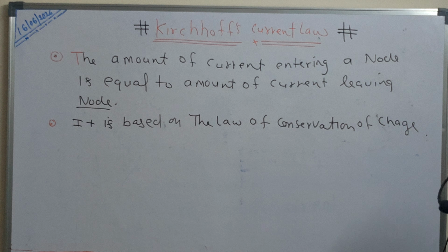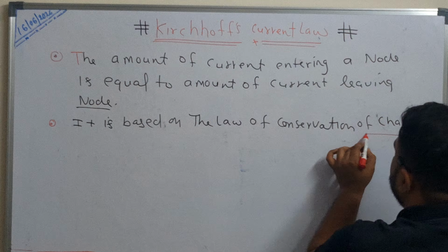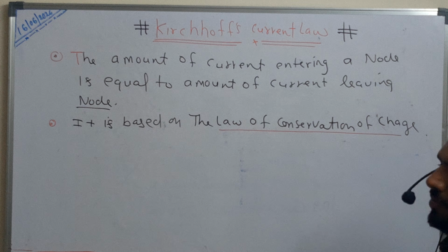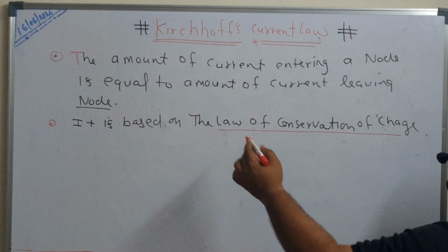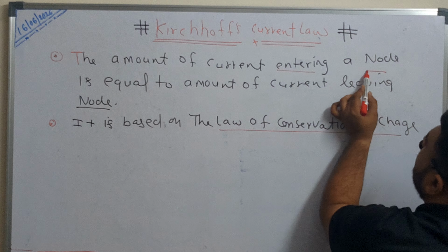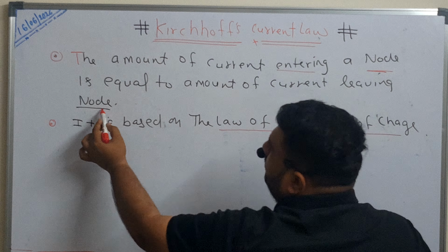This is a very important line. Please highlight this. It is based on the law of conservation of charge, and first thing, the amount of current entering a node is equal to the amount of current leaving a node.